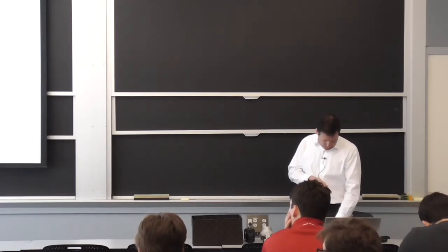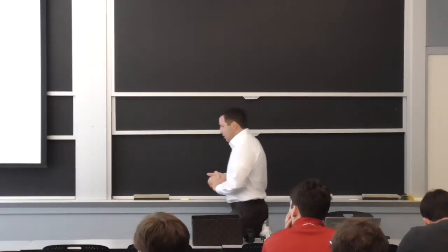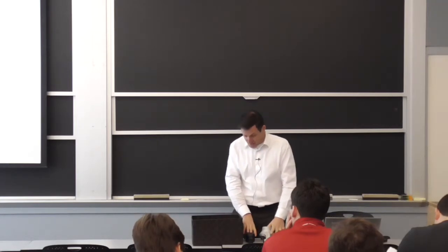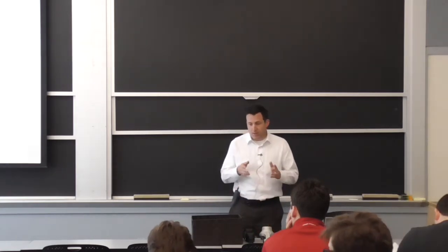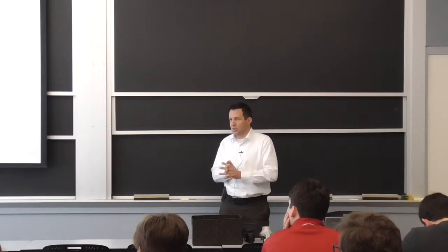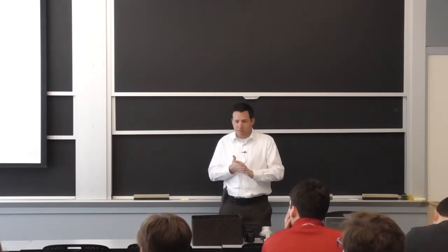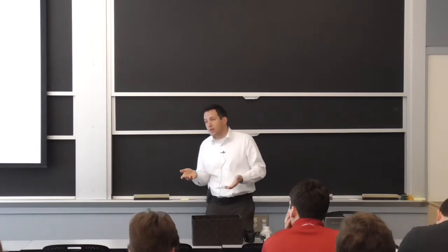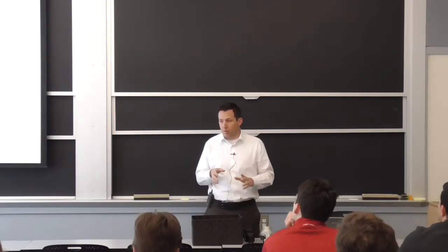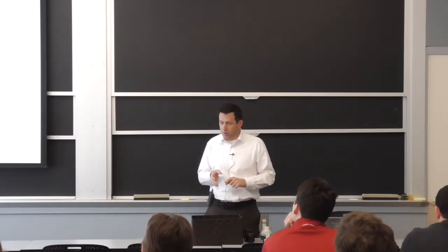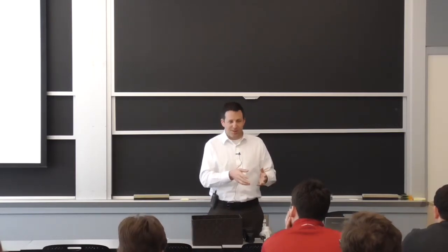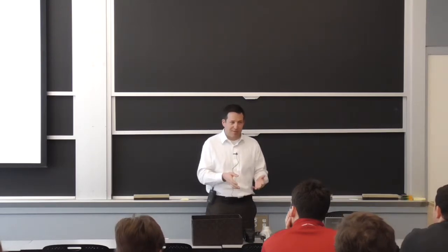Okay. So what we're going to do is start with material selection. I've got a few examples that we'll go through at the end. There's always a number of steps that you have to take to build something. The first thing is to decide what the performance criteria are. A lot of the time it is overall cost. And actually, Professor Eager has a full 12-hour module available online on material selection where he shows that for a given application, like if you're building a road, you'll use aggregate because it's really, really cheap by the ton.